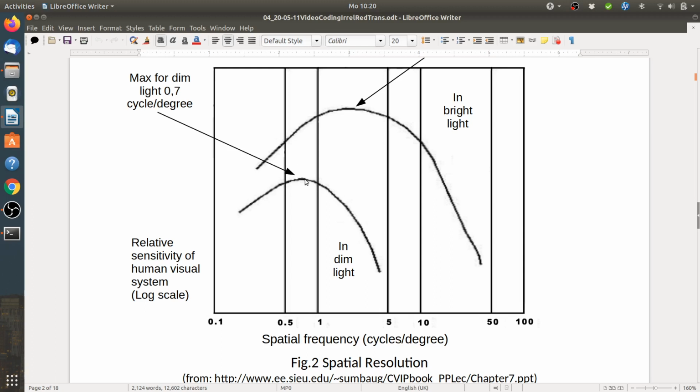But at low frequencies, where the eye is very sensitive, we can only afford low quantization errors before the error becomes visible. So here we cannot save in the peaks, but at high frequencies is where we can save many bits. This is the important part: the eye is less sensitive at high frequencies, and hence we can save many bits in those regions.